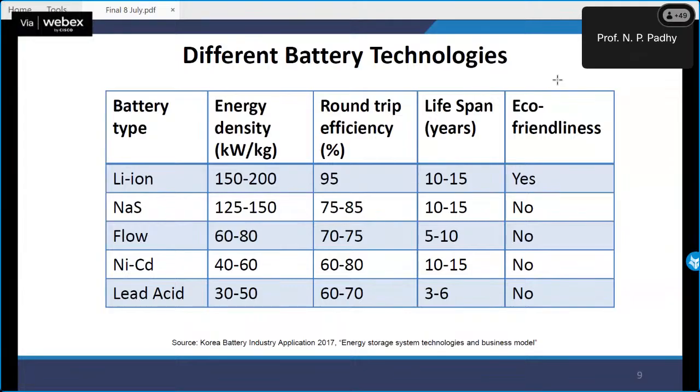But the challenge here is that the water which has gone to the downstream can again be brought back to the dam using electricity, right? So if I have generated X megawatt hour of energy through a hydropower plant, and if I would like to take back the similar water back, then I need more than X megawatt hour of energy because of efficiency and other losses.